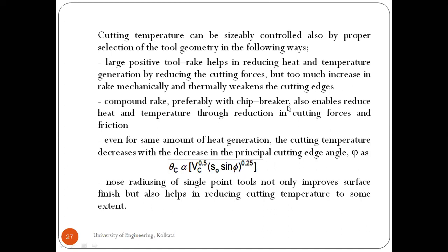So that is not really desirable. So chip breakers are provided so that they can break the chips and remove the chips from the cutting zone, and this enables reduction in heat and temperature through reduction in the cutting forces.